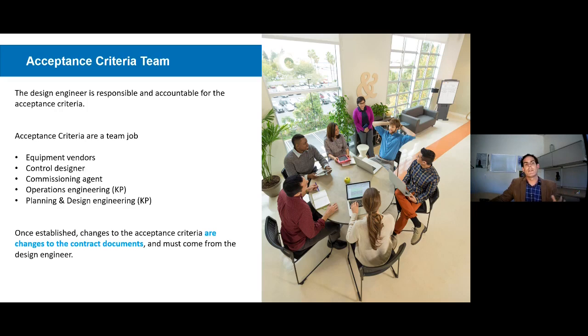We've seen this really more than anywhere else on rooftop package units. The sequence that I would have written up, in my caffeine-induced frenzy, and the sequence that actually arrives on the job site with a standard Trane unit are two different things. And so that all needs to get vetted out and hammered out during the design phase. It really does take a village to write these sequences and the acceptance criteria for them.